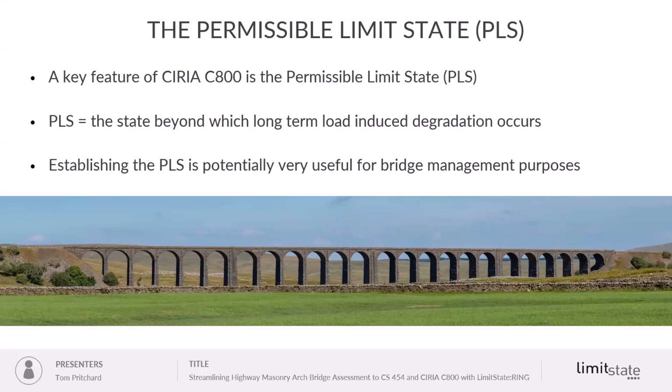However, mobilizing the horizontal passive soil pressures requires large displacements, making it more relevant to an ultimate limit state model than to your normal everyday situations where joint movement and progressive structural degradation through small displacements are more of concern. And like we say, establishing the permissible limit state is potentially a very useful tool for bridge management purposes.